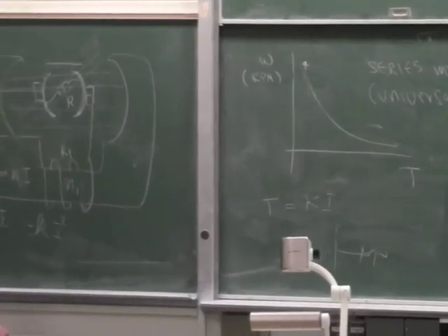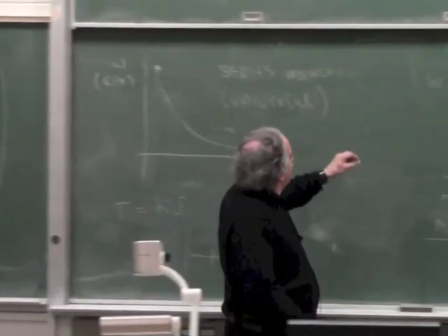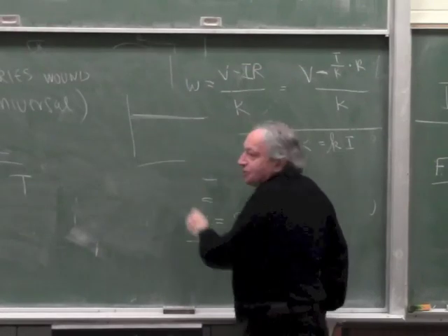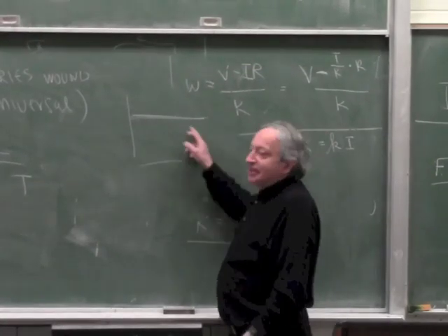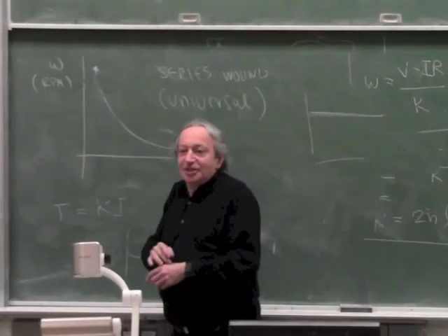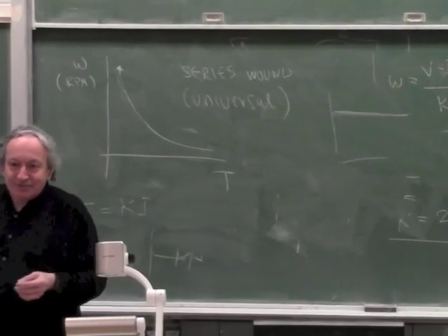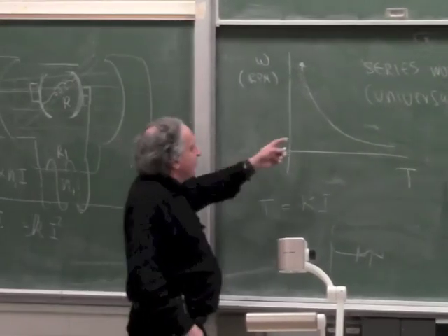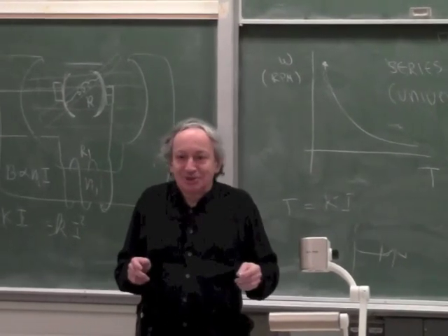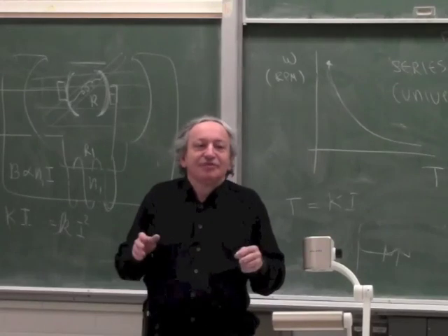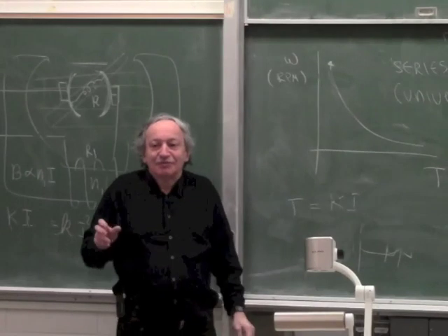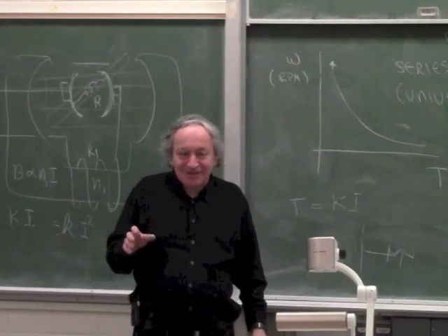Just like when you had the PMDC motor, and the PMDC motor had a curve like this, it just moves up and down the curve as the load changes. But here it moves up and down the curve and the speed is almost constant. Here it moves up and down the curve and the speed can change 100 to 1 depending on the design of the motor. But this is very desirable because this is like having an infinite automatic transmission. So think of it, the purpose of an infinite automatic transmission is to generate this curve, so that you can always get the full power out of the motor. Okay, in a car, say.